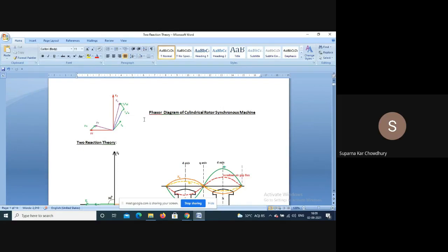If the MMFs are sinusoidal and we have a constant reluctance, then MMFs divided by the reluctance give you a sinusoidal flux. So the corresponding EMFs are also sinusoidal. So all quantities are sinusoidal, and we can simply add them by vector addition, treating them as sinusoidal vector quantities.